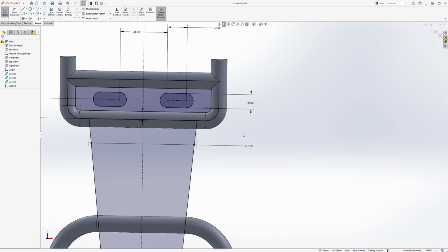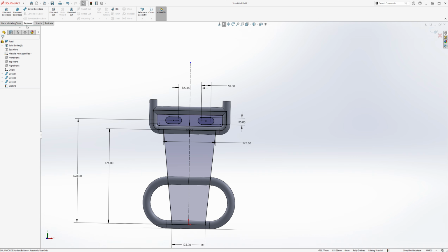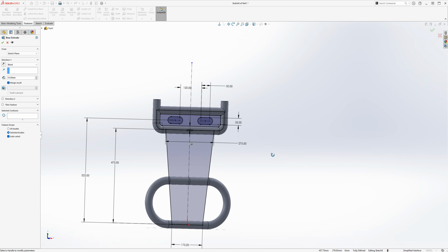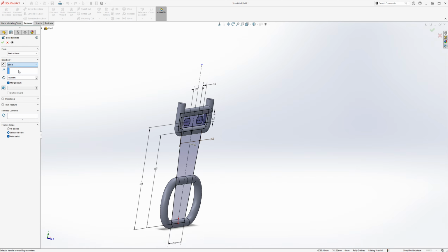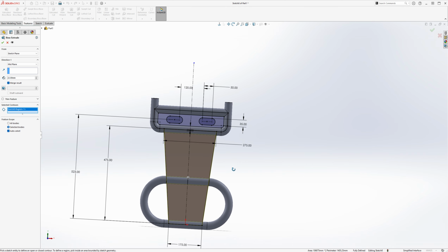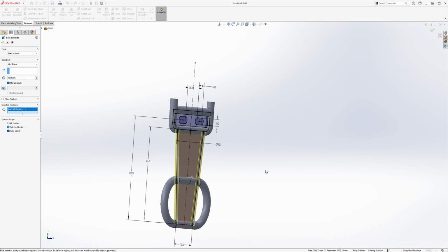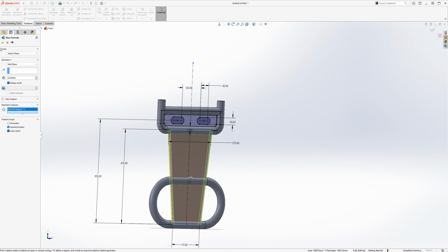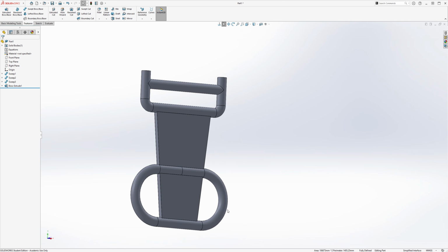So now we are going to do our extrudes. We'll go to feature, extrude by space, and we'll have to extrude it mid-plane, and we'll have to do this 2 times. So let's start with the Dorito chip. The Dorito chip is extruded a depth of 22. Select contours and just the Dorito chip. Select OK.